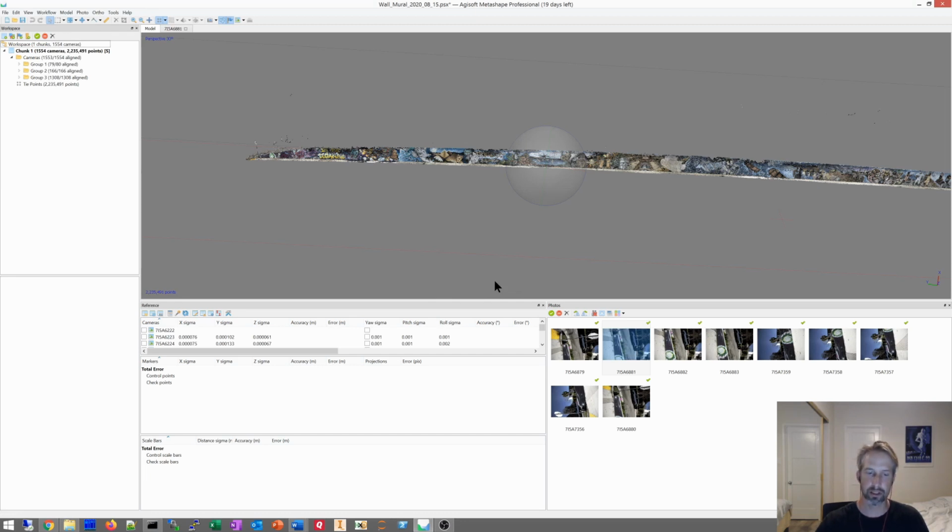After doing that, you can optimize your camera placement, remove low quality points, optimize cameras, and also use gradual selection to remove the low quality points. But that's already been done, and we're in good shape on this model. I've already completed those steps, so I'll skip directly to marker detection.